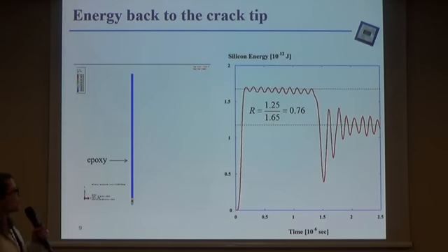To examine the effect of a reflected stress wave on the crack speed, we had to ensure that the energy is reflected back from the epoxy resin. To calculate the energy that comes back from the epoxy resin, we performed a dynamic finite element analysis, in which we took a cross-section of our assembly, where at the bottom there is the silicon sample, relatively there is the epoxy, and at the top there is the aluminum molding frame.